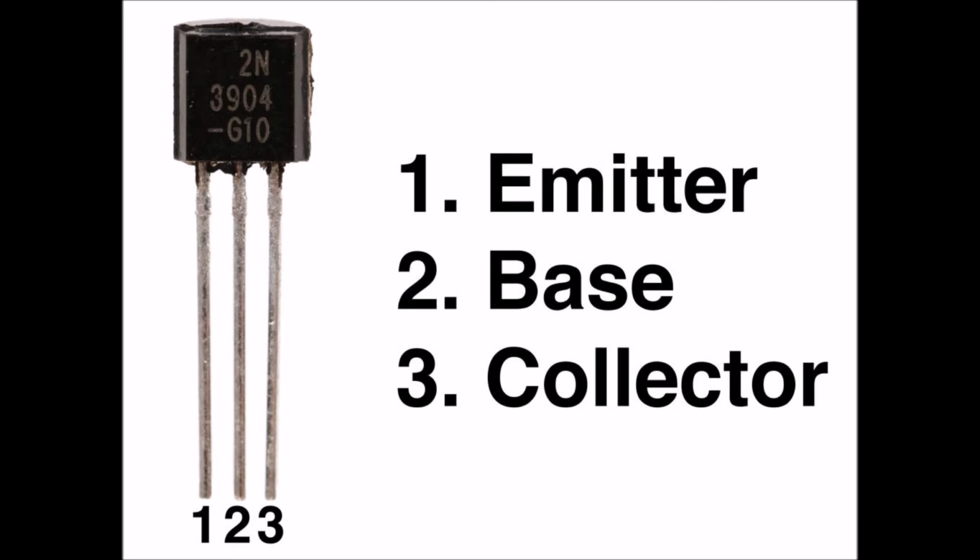A common base amplifier offers better stability than most common emitter circuits do. By better stability, we mean that the common base circuit is less likely to break into oscillation, generate a signal of its own, as a result of amplifying some of its own output. The main reason for this good behavior is the low input impedance of the common base circuit, which requires the input signal to offer significant power to drive the system into amplification.